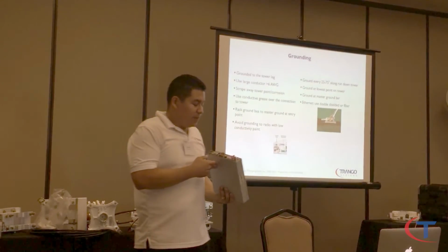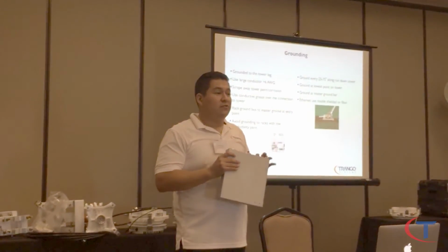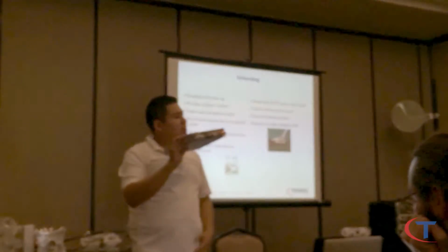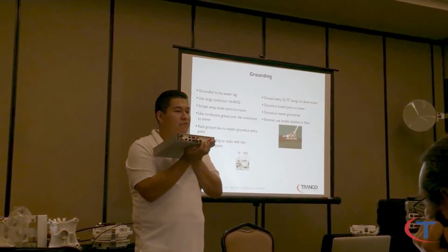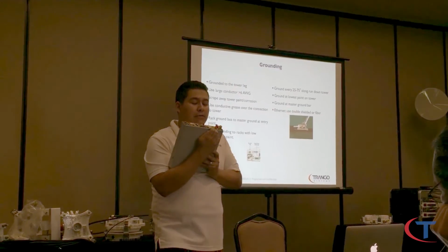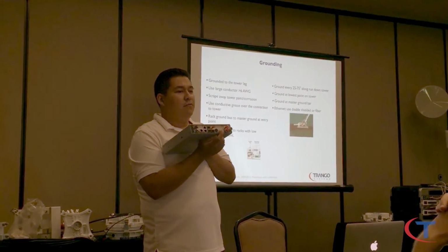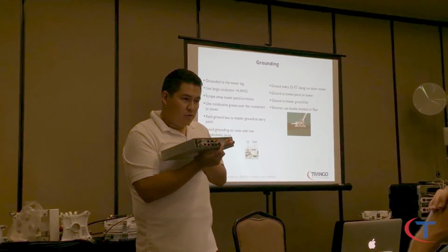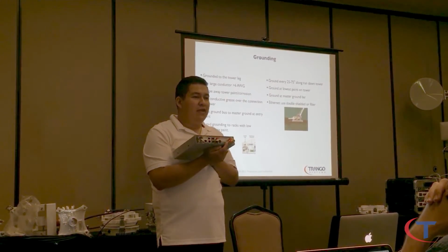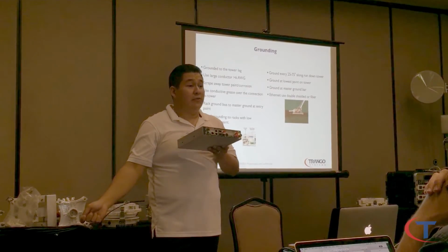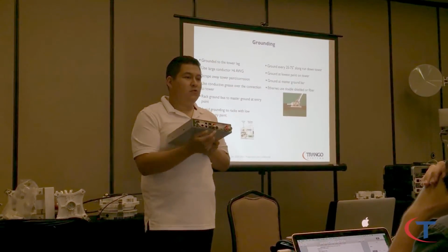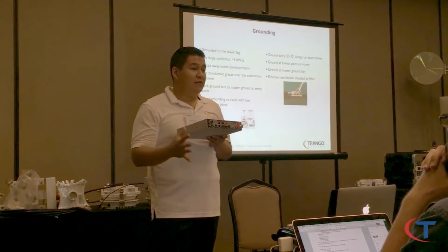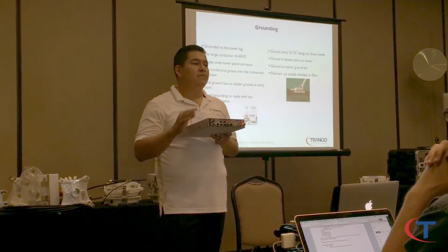Now, talking a little about power, I want to go into power redundancy. It's a good feature on the radio. On the IDU itself, you have a 3-prong connector in front. The middle one is the ground, and both left and right are negative 48 power. So what you do is you have one side going to the AC, pretty much coming out of the wall utility grid, and you can have the other one coming from a backup battery, solar power, generator, whatever you want to have. As long as it's a clean signal, neg 48, it's going to be fine.